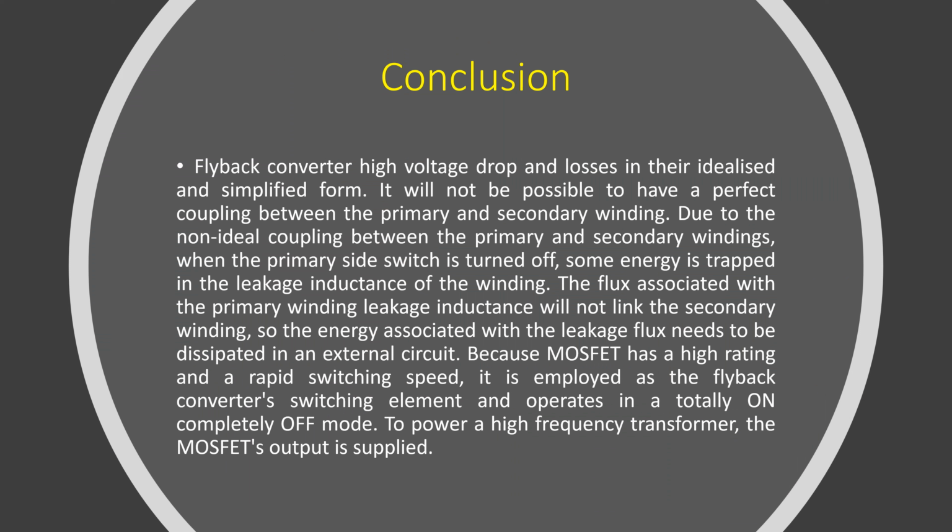As a conclusion, flyback converters have high voltage drop and losses in their idealized and simplified form. It will not be possible to have a perfect coupling between the primary and the secondary winding due to the non-ideal coupling between the primary and secondary windings. When the primary side switch is turned off, some energy is trapped in the leakage inductance of the winding. The flux associated with the primary winding leakage inductance will not link to the secondary winding.